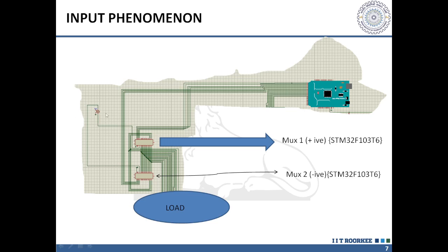We know from the previous slide that I have to give the current between two electrodes at a time. There are 20 electrodes connected to the mux, and at the same time I need to activate only two wires, to which I want to connect my voltage-controlled current source.